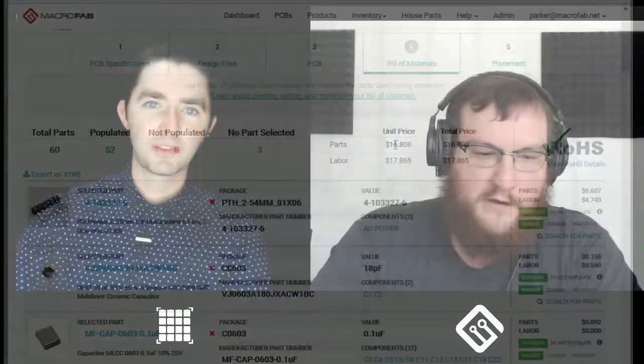Right, and this is akin to almost any other manufacturer I've ever heard of. When you're doing assembly, it's better to have stuff that's already on the line. It's just that in this case, you have a house part number associated, versus assembly jobs I've done in the past where it's just like, all the decoupling caps, Panasonic resistor. Yeah, exactly. 0603, if it's 5% or better, I don't care, right? 10K, and 5% or better, fine. And the idea behind the house part numbering is that it's like MF, Res, 0805, 10K. It's easy to search and easy to find the part you're looking for, instead of like, now I need the 0805, 10K. What's that Panasonic number?